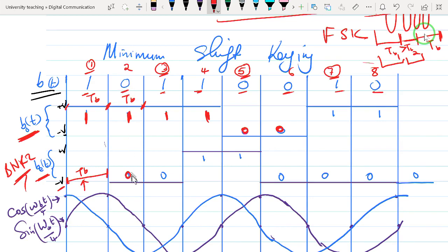So while it was 0, we are going to be counting it twice, so 0 and 0 here. Then the fourth one is a 1, and therefore we are going to shift, as you have seen, to bipolar non-return to 0. The 1 is going to be represented by a positive voltage. So this is going to be a 1 counted twice. Number 6, or the 6th bit, is a 0. We have it represented by 2 zeros here because of 2 bit durations, and the 8th one is also a 0, represented again with 2 bit durations. That is the first step, that of separating the odd from the even bits.